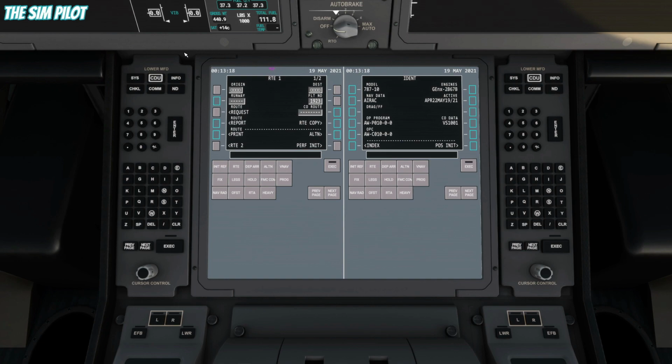So to recall the flight plan from SimBrief, first you need to generate the operational flight plan in SimBrief, obviously, and from there you can hit this request button and it will give you two options: load flight plan from game. I think this is when you save a world map menu flight plan, you can load it, which I have never tried. I usually go to SimBrief flight plan and use SimBrief for my flight planning. And when you click this, you will see it is going to start loading your flight plan from SimBrief.